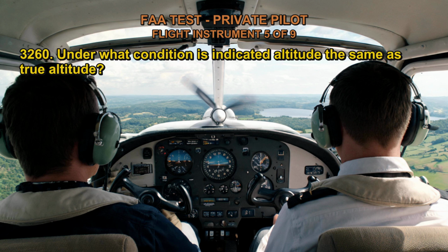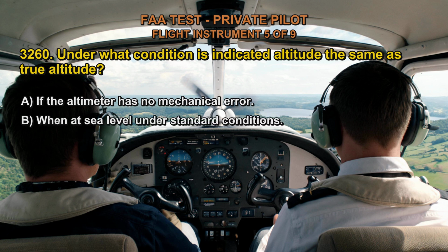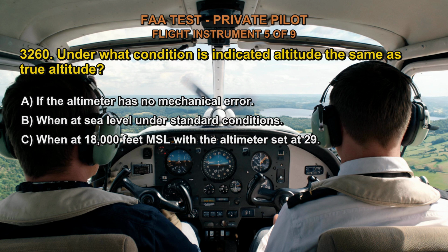3260. Under what condition is indicated altitude the same as true altitude? A. If the altimeter has no mechanical error. B. When at sea level under standard conditions. C. When at 18,000 feet MSL with the altimeter set at 29.92.